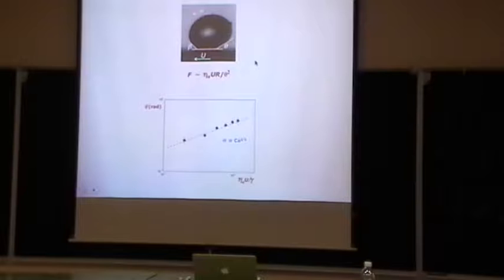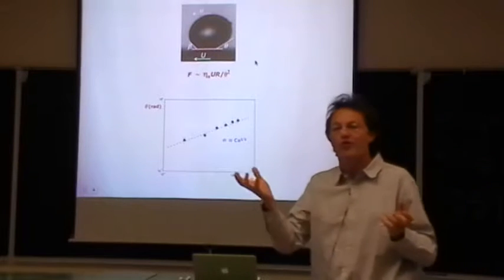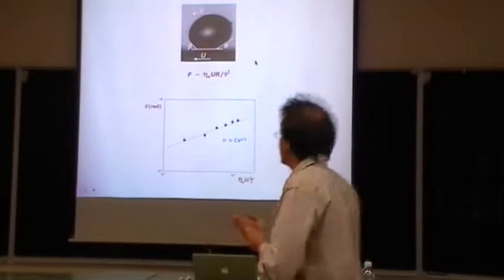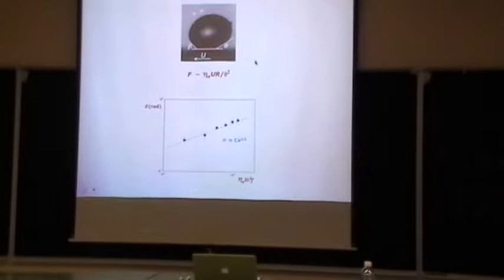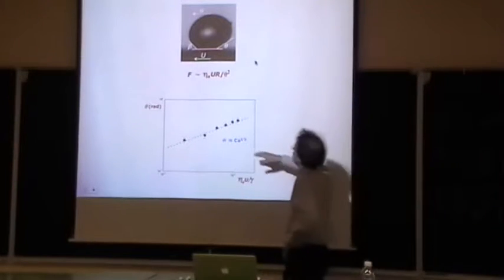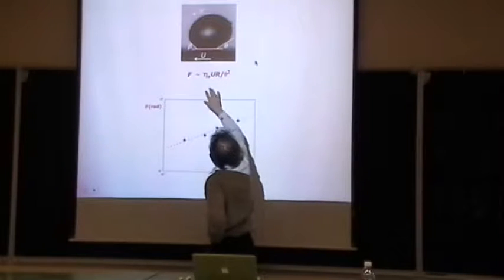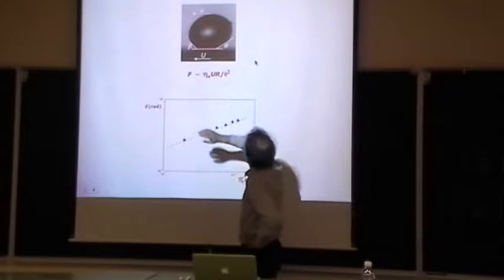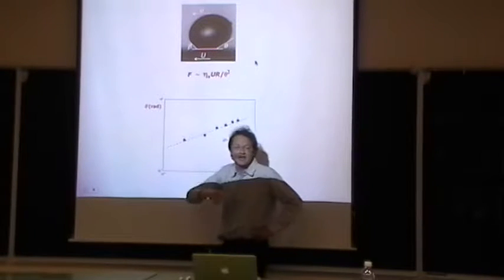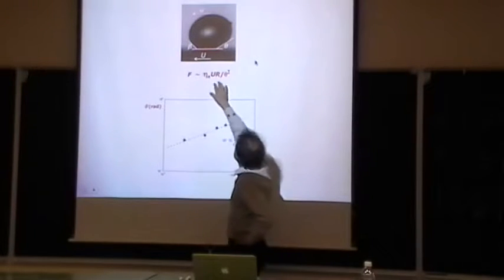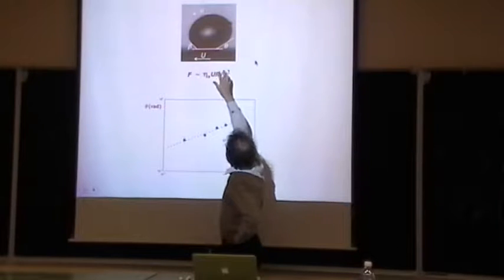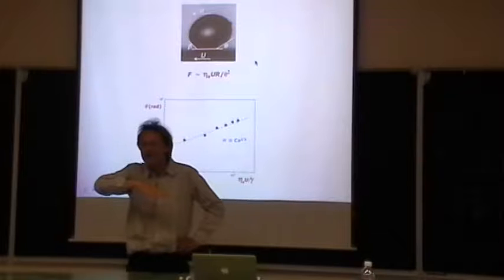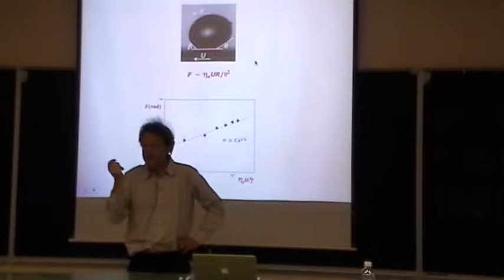And so very naturally, you can think of a lift force generated by the lubricating film in the corner, which is below. And so if you write such a force, which is really in classical textbooks, you say, well, a lift force in this case should be related to the viscosity of air, which is a lubricating fluid, the velocity of the air below your drop, the size of the drop, and the apparent contact angle that you have, the corner angle below the drop, to the square. So it's very sensitive to this angle.